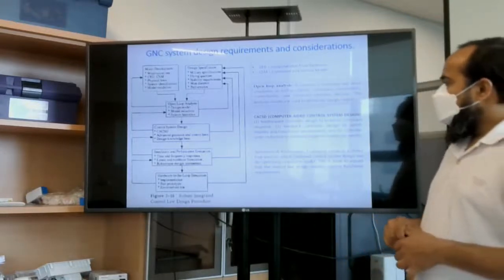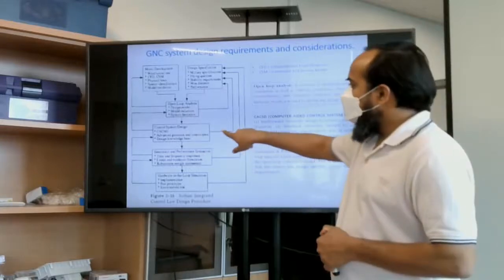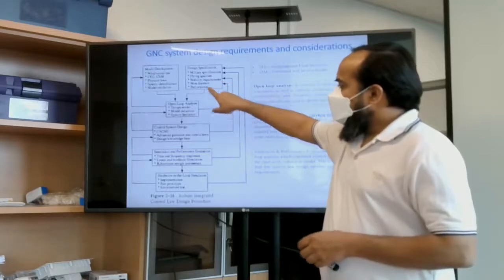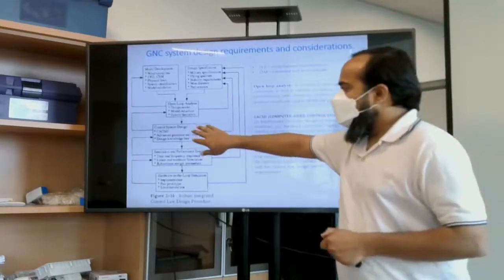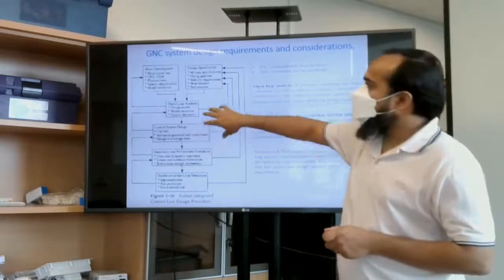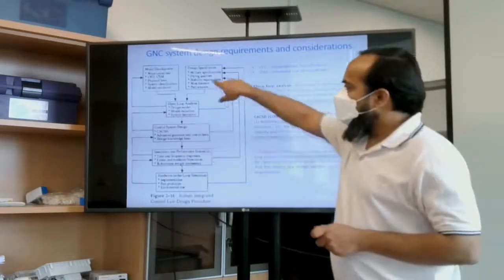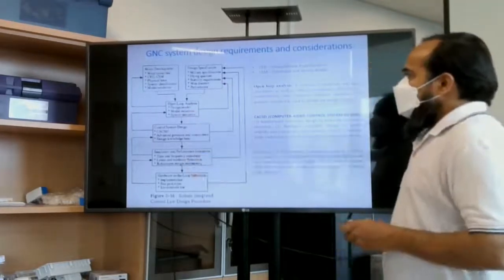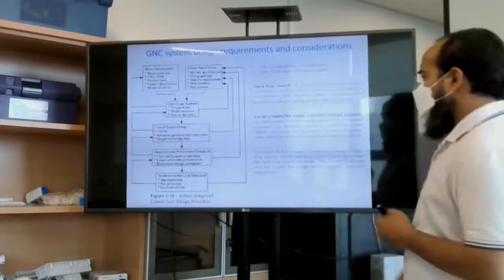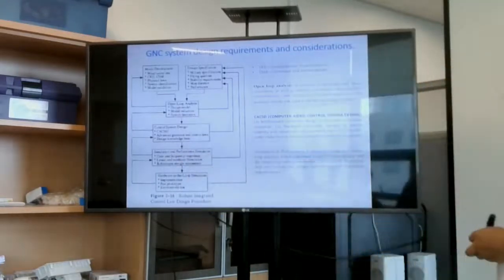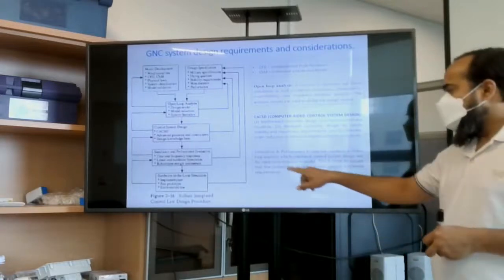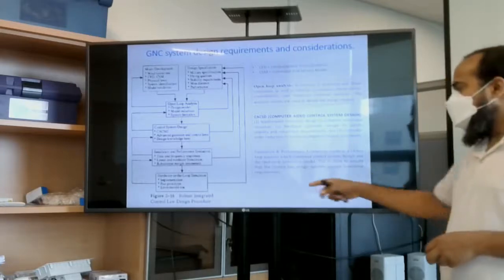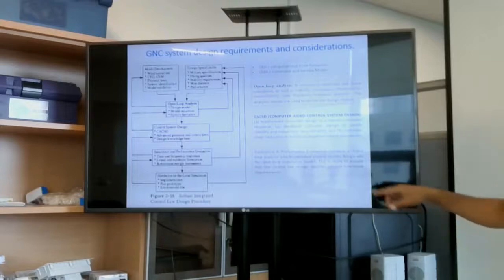Okay. Now this is again feedback, or closed loop, back to the design specification, because until the closed loop system satisfies the system specification, it will go back and do the analysis again, and come here, and also model development and then simulation performance evaluation. It conducts a closed loop analysis which combines control system design and the open loop simulation model. This is done to ensure that the control law design satisfies the control functional requirements.